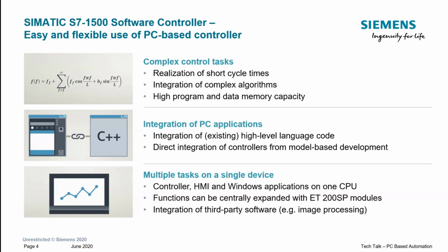Now at the bottom, we talk about having the controller, the HMI, and the Windows application all on one device. And you may have noticed on the previous slide that the Open controller did indeed have a DisplayPort connection. Some of the IPCs have a built-in touchscreen as well. What this means is we can have bundles that allow us to run an operator interface, so a WinCC application in the Windows side, and that will directly talk to the software controller. So we've now got just one piece of hardware that's the operator interface and the PLC itself. So reducing space, reducing cost. Now, obviously, we can expand this with all sorts of header modules.